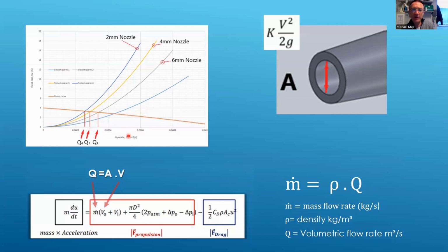So if you have, for example, a 1 mil nozzle, what you're doing is putting a severe restriction in the flow of the fluid and reducing your mass flow rate and reducing the thrust in the boat. So somewhere along that line, you're starting to affect the thrust, and that's what you need to examine.